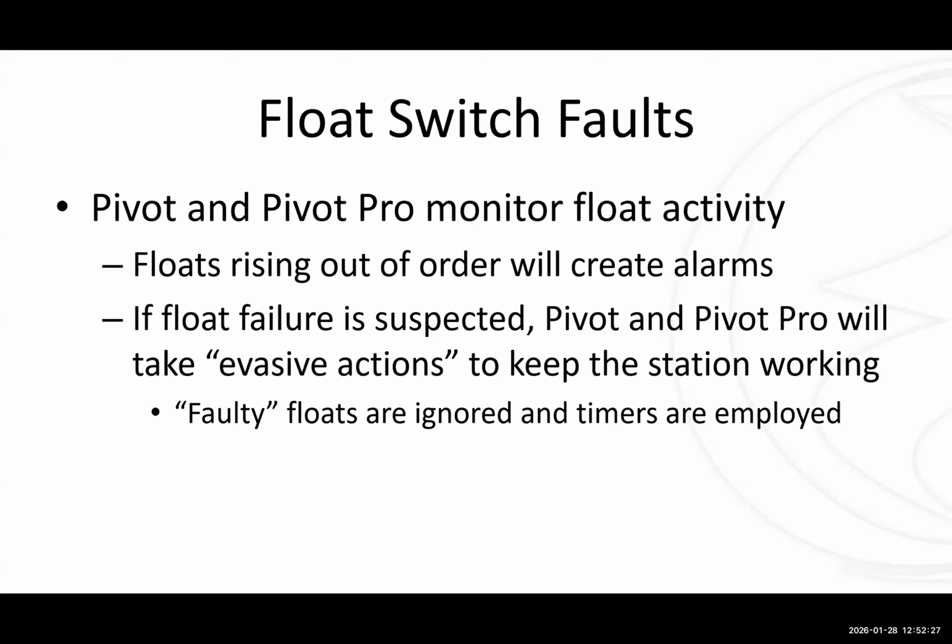It'll start both pumps and run until that high water float drops out, but it'll actually run a little bit longer, like 15 or maybe even 20 seconds, again to get that water level down a little bit further in the basin before it shuts the pump off. So if it doesn't think it can count on a low float to stop it, it switches over to a timer-based operation to keep that pit dry.